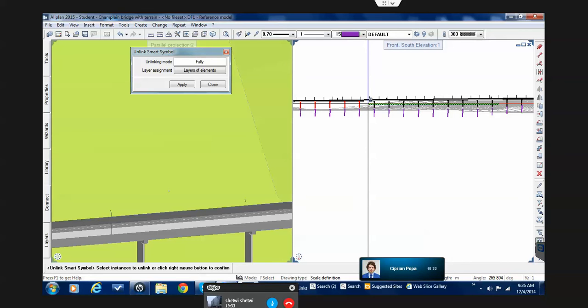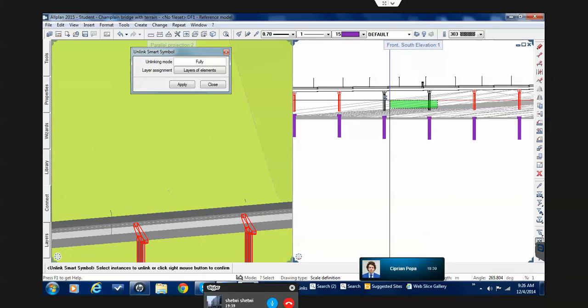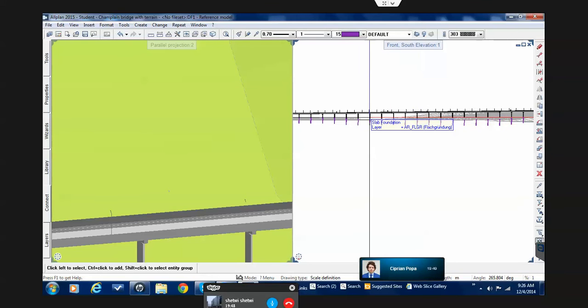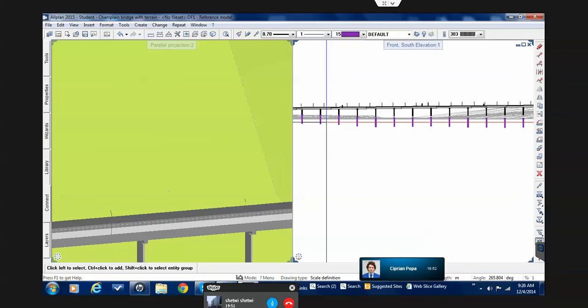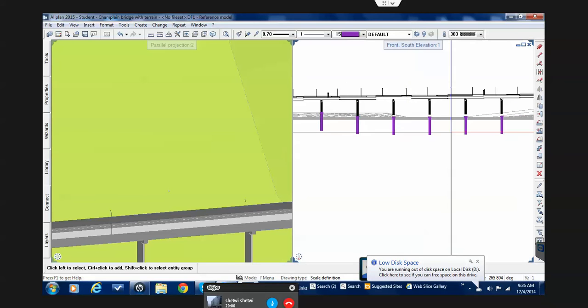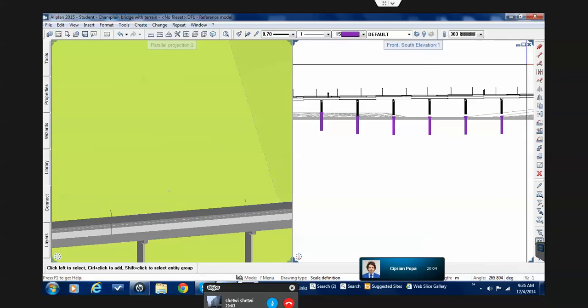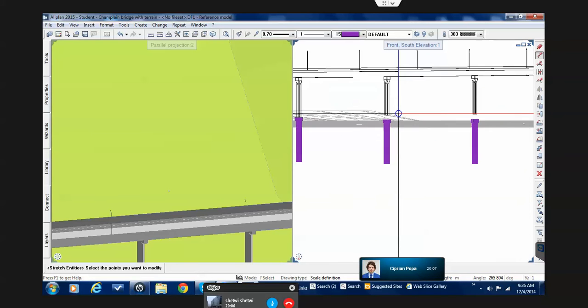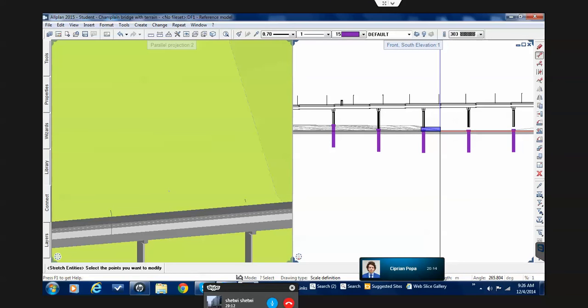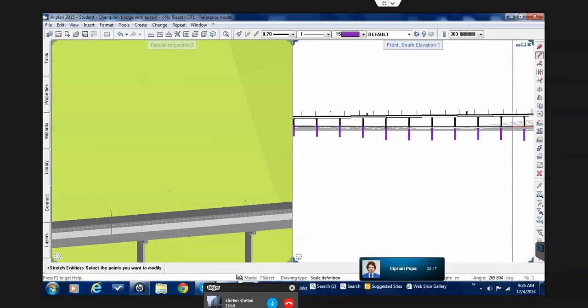and it's important to have the foundations at the same level, so it's good the way you did. Okay, so we would need to place this foundation as the lowest pile, and then adapt the others. So it's good that they have the same height. The foundations have the same height, are at the same z coordinate, and we just change the length of the bridge footing. So well, here I see that they are constant, so I can select a bigger area.